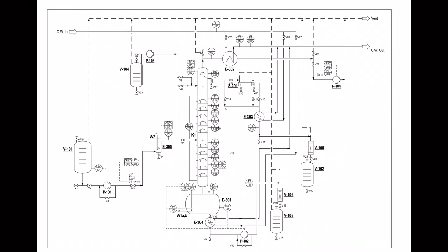For the distillate top sampling, there are two options, whether you want to take your sample at this part or this part. For this part, you place a beaker below valve V11. Then go to your control panel and set the reflux divider to position 1, which is total distillate.